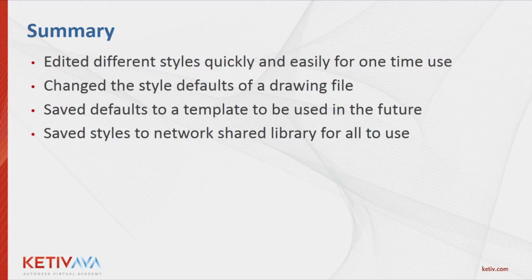And the library so that we can avoid any of those style conflicts, style error messages, whatever kind of annoyances that may occur with these styles. To avoid all of that, we worked with those templates and those styles libraries. And then for those of you who want to share these styles with users across your network, we also showed you guys that it's possible to share them with those application options, your project file, and those network locations. So yeah, that's pretty much it.